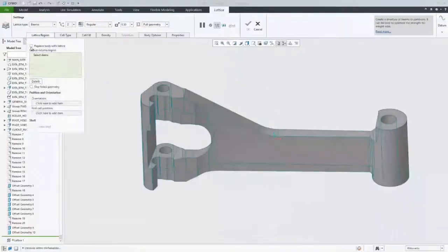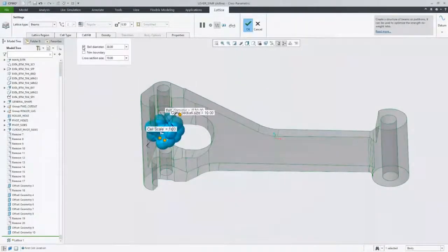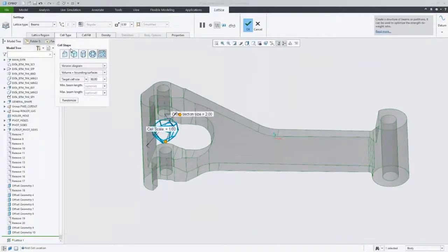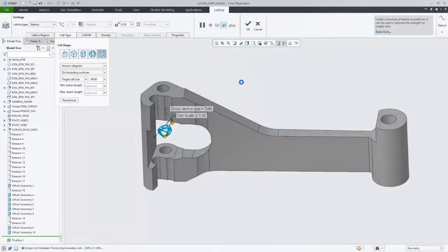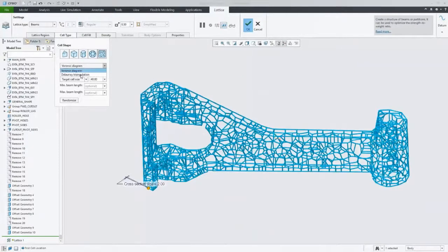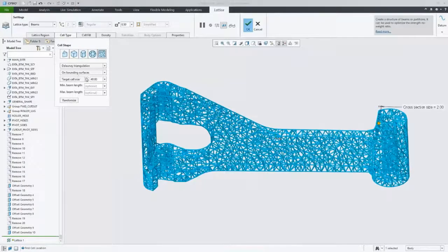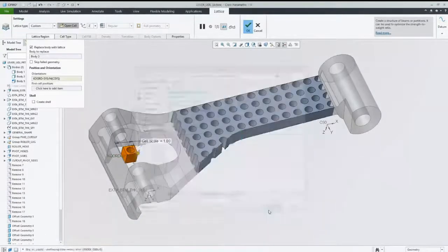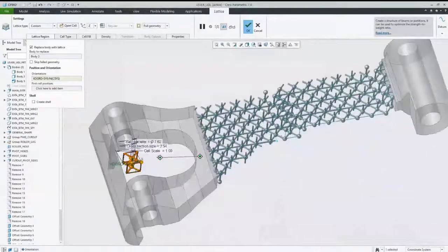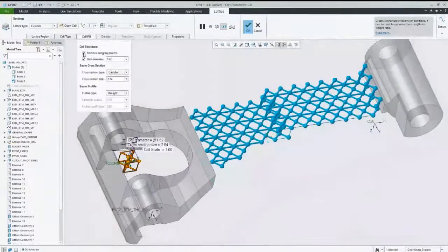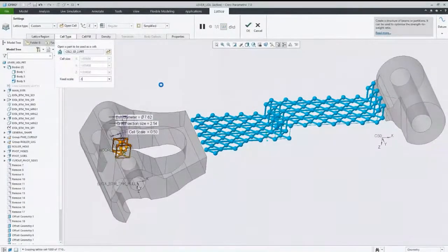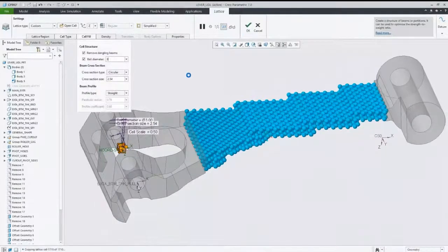innovation. Stochastic lattices are useful for producing medical devices and products which require heat transfer applications or shock absorption. In Creo 7.0, you can now both create stochastic lattices that follow hard edges and develop them with triangular mesh structures using the Delaunay algorithm. Lastly, custom cell improvements give you the flexibility to create lattice structures based on non-BREP geometry to better serve your needs.